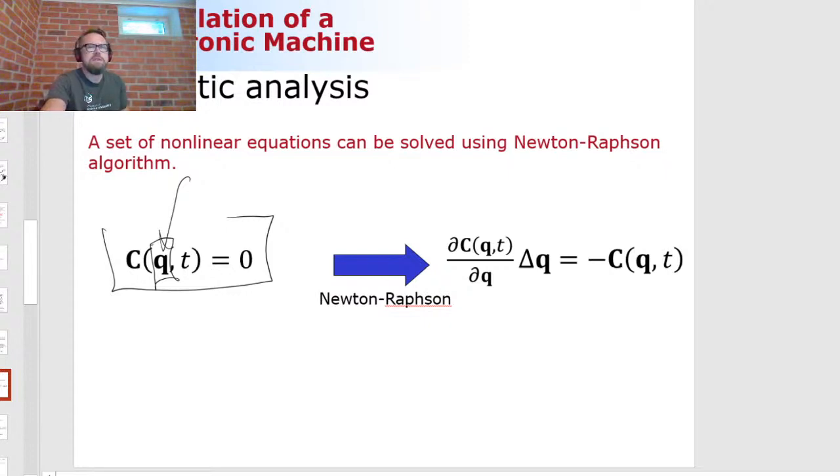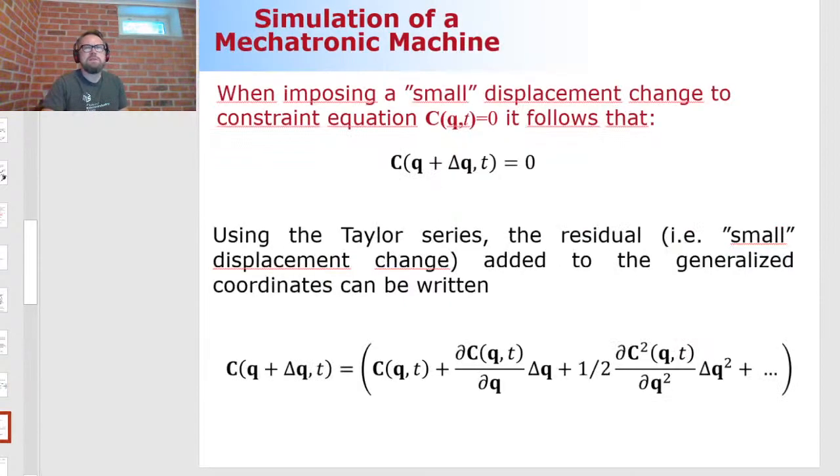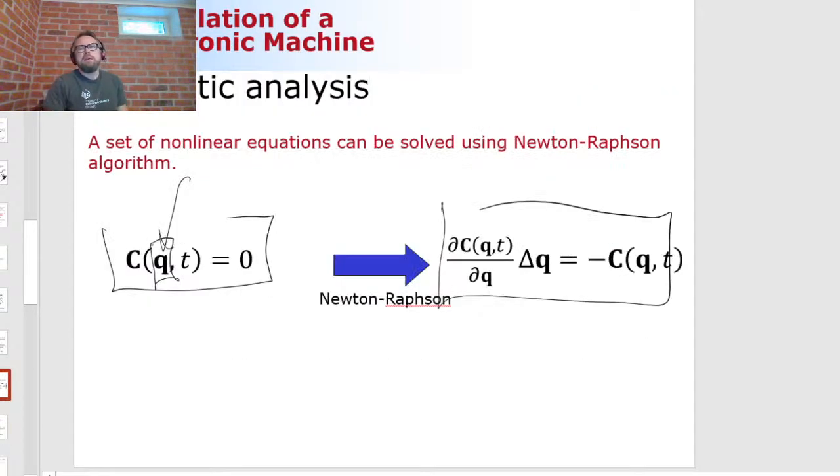And this is the process to do it. I think there is a nice derivation of how to get this equation in the lecture notes. Let me see if I remember correctly. Was it here as well? Yeah, it's here as well. Okay, so that's called the Newton-Raphson procedure. In the Newton-Raphson procedure, you're basically solving for this delta. Delta tells you how you should update your coordinates to get a better solution. Usually when you do it once, the solution may not be acceptable. You may need to do it twice, maybe even more than that, and that's where the iterative nature comes from.